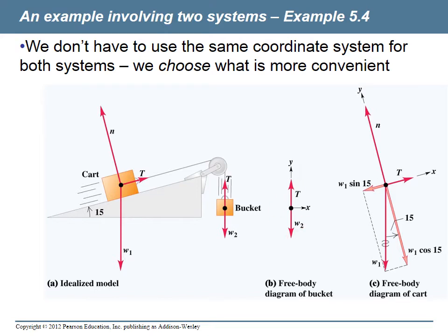So that's one. That gives us one equation there. And then we free body diagram the cart here, and we call that W1. We just draw that dot here. We have some tension that will act off in the x direction since we've oriented our axes to be parallel. So the x direction is parallel and the y direction is perpendicular. Then the tension acts in x, and also the parallel component of the weight would act in x, right? And it would act back the other direction, back this way. And that one we said was mg sine theta, right?